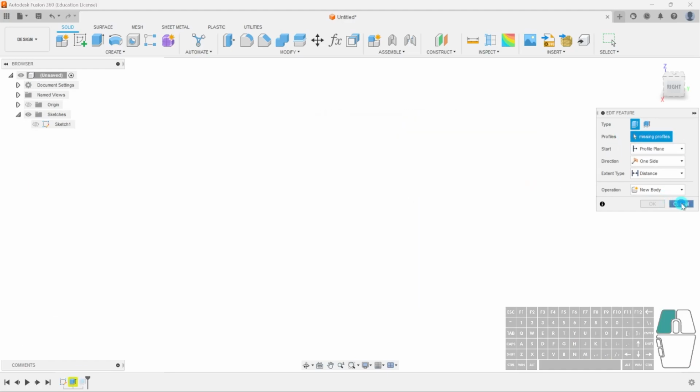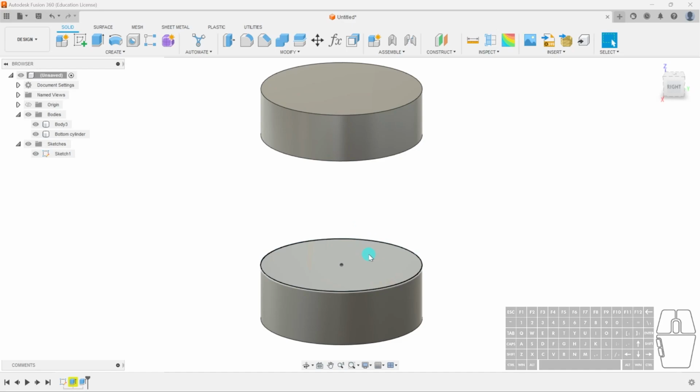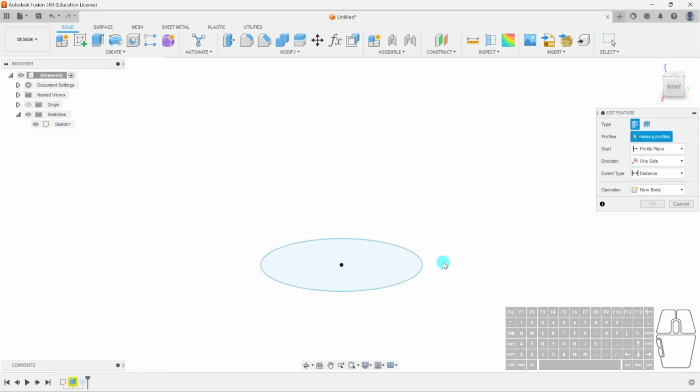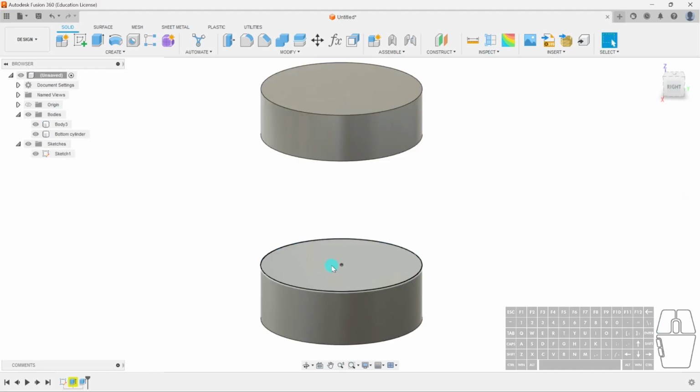And what that means basically is, if you remember we had our sketch and we extruded from this sketch. When I made that extrusion, this one here on the top, I didn't select this sketch, I selected the face of the previous cylinder we used. But now that cylinder's gone. So Fusion's going to kind of freak out a little bit, but it's smart enough to say, okay, you messed up, you're probably stupid, but I think this is what you want. That's why it's yellow here. It's saying, hey, don't worry, I got you, fam. You stupid, but I got you.